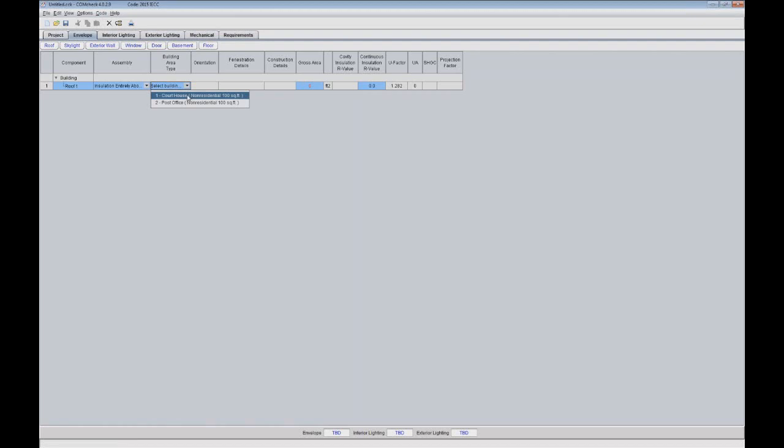And let's say on the very top floor is the courthouse. And then I enter the square footage. So now for roof, it depends on the insulation placement. If I'm not insulating at the roof deck and I'm insulating down at the ceiling level, I'm calculating at the ceiling level for my square footage. Insulation placement for the roof.